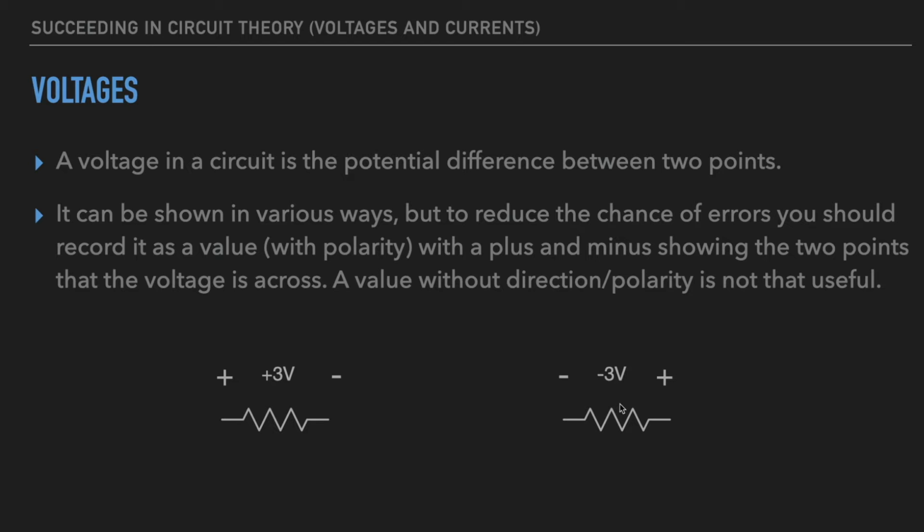On this resistor, we have a minus, so our plus is actually the negative end of the resistor. So whatever the sign you see in front of the actual number, that basically will go on where the plus symbol is. So we have a negative here, and we have positive voltage here. So this voltage minus that one equals -3. So this end is the negative end, this end is the positive end.